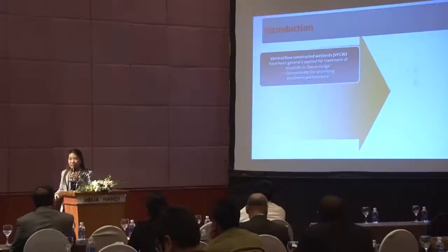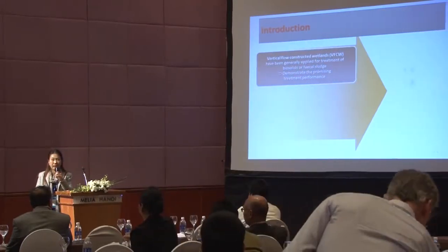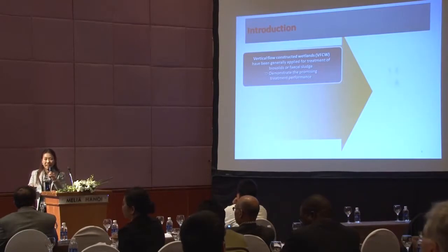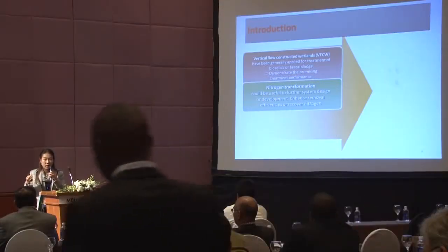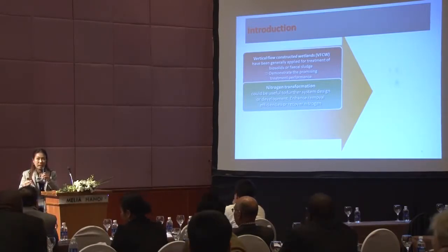From our 15 years of experience at AIT, we have confirmed that vertical flow constructed wetlands have promising treatment efficiency for fecal sludge treatment. If we know the nitrogen transformation inside the system, it will be good and can help with the design of the system. Whether you would like to increase treatment efficiency or reuse the nitrogen, we can also model it if we know the system well.